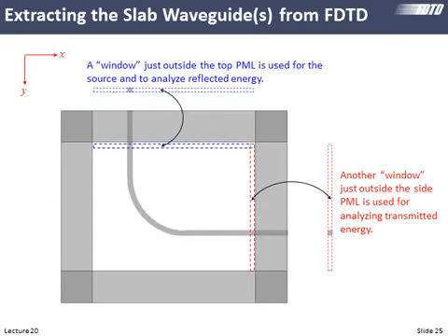So at first, we won't know anything about our waveguide finite difference analysis. We think we're doing a two-dimensional finite difference time domain simulation, and we will. So we build our grid, we build our PML, we build the waveguide on it, and here maybe we're studying a waveguide bend. We want to launch energy into our waveguide. We want to see it go around the bend and exit. And maybe we're studying how much of that is leaking out so we can figure out how tightly we could bend our waveguide without losing the energy.